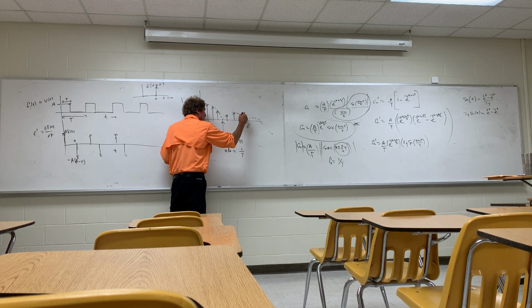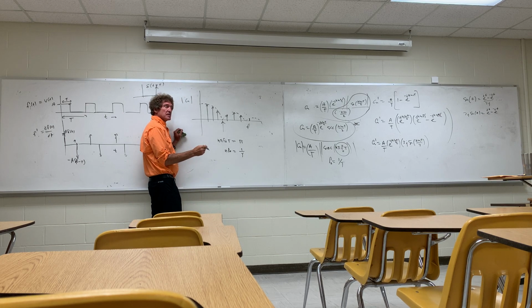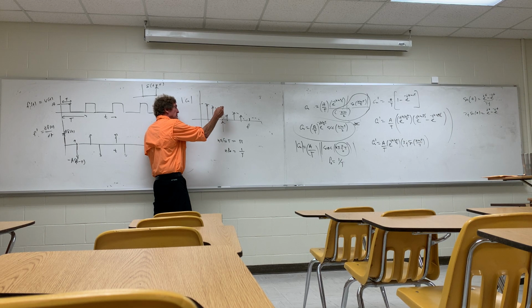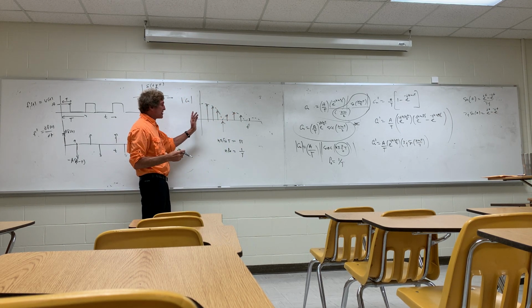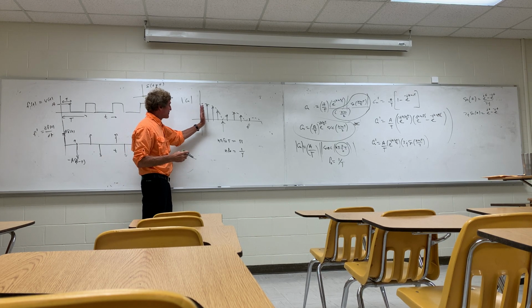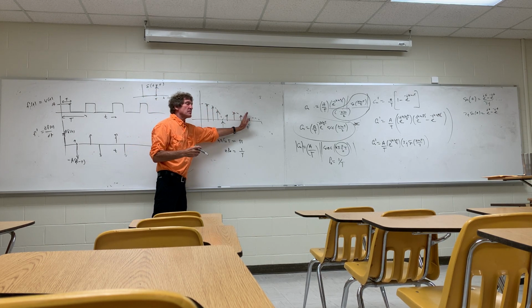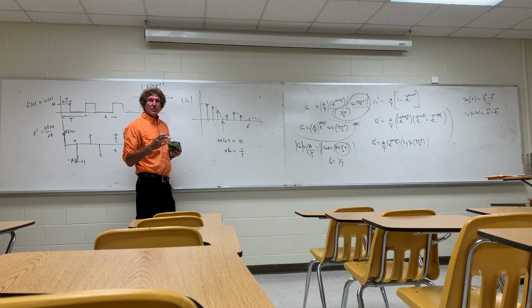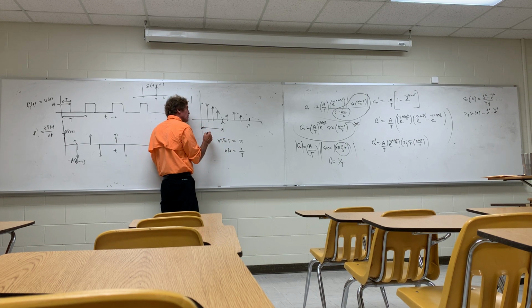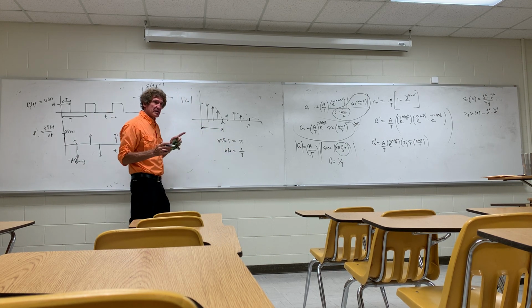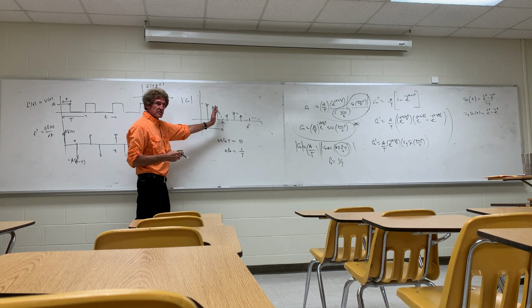I'm not going to have enough time to go through all this. When you look in the frequency domain at where the signal is, this is going to be proportional to the voltage strength, not the power. This is how it looks in the frequency spectrum. When you have a square wave like that, you have frequency components all over the place. When they talk about bandwidth, it is usually this range here to the first zero, because that's where most of the energy is.